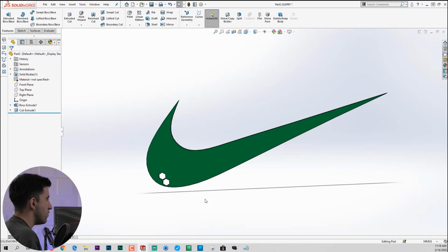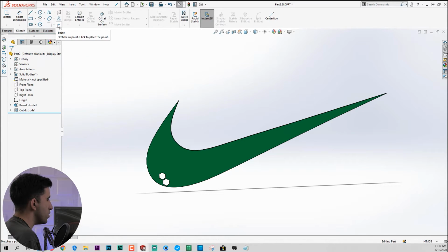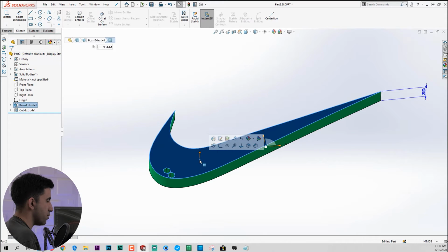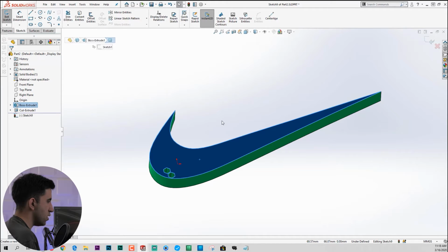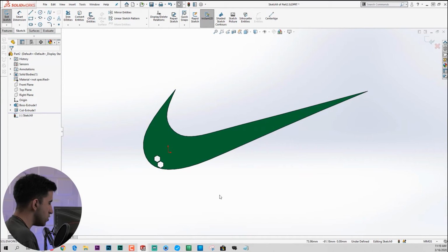All you need to have is points. Wherever you place a point on a sketch driven pattern and pick a feature, that feature will appear on that point. So I'm gonna fill up this logo with a bunch of points with the right distance from each other to create a honeycomb. Let's see what I do. I'm gonna go ahead and draw on this top surface of the component and click sketch to activate the sketch mode, press spacebar and make it normal to, like that.